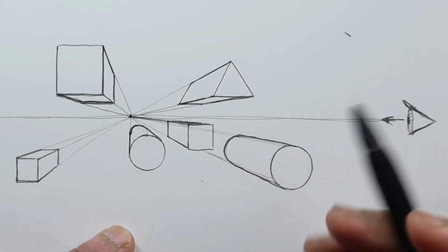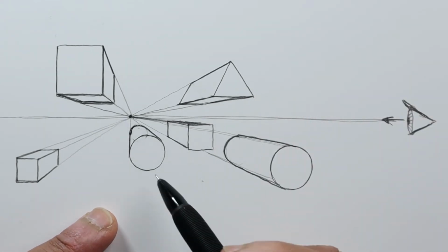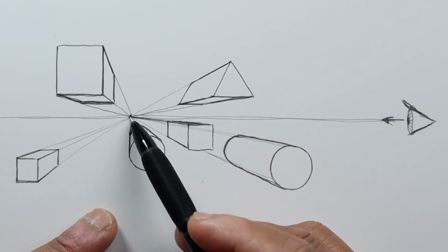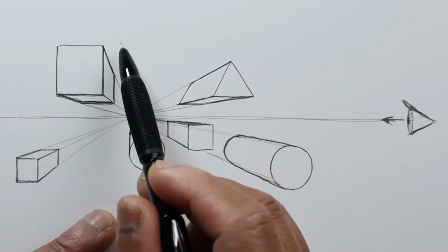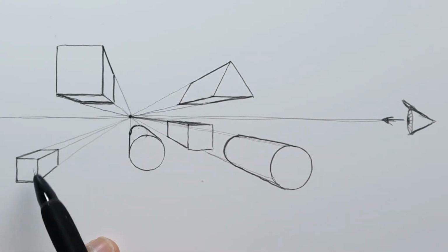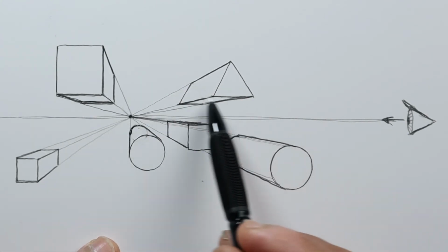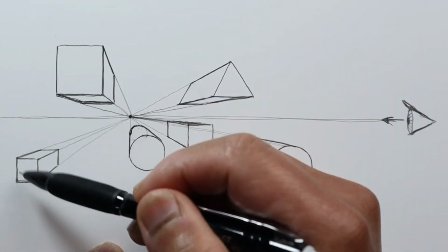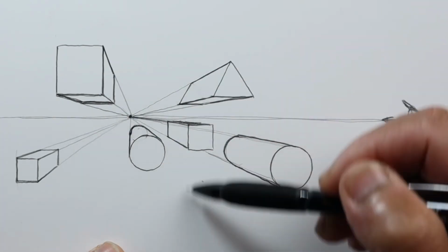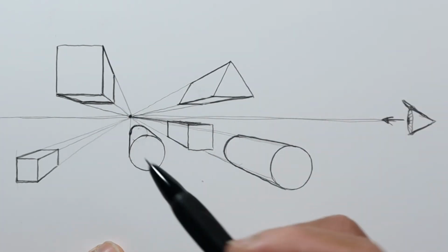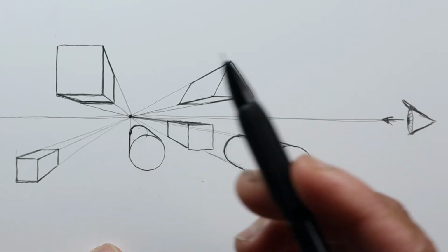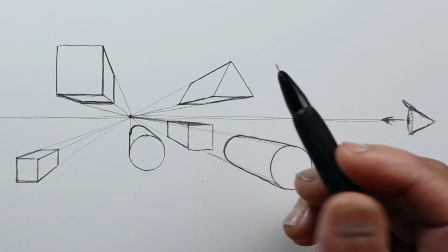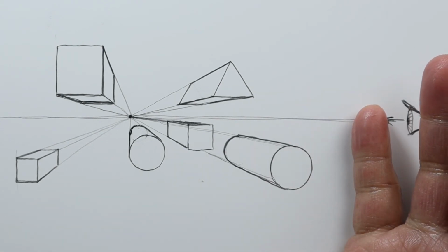And that's basically what one-point perspective is, where one set of parallel lines converge to one point. These parallel lines do not converge. As you can see, all of these lines here, our horizon lines, are all parallel to each other. As well, all the vertical lines in this drawing are all parallel. They're not converging at a secondary point, which we'll talk about in a later video, where I talk about two-point perspective and three-point perspective. So that's the basic gist of drawing in perspective.